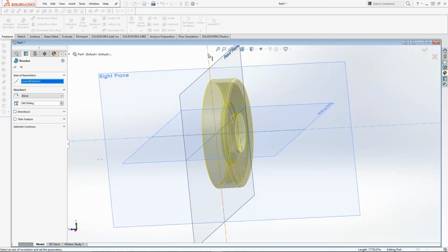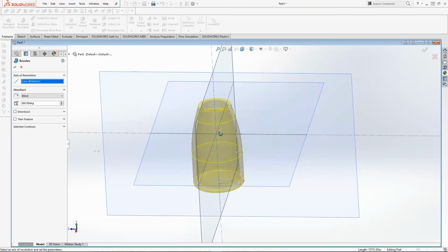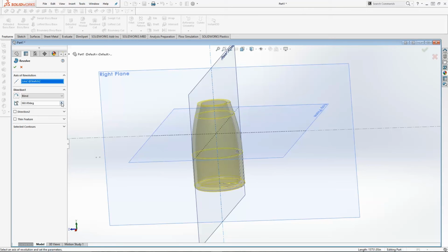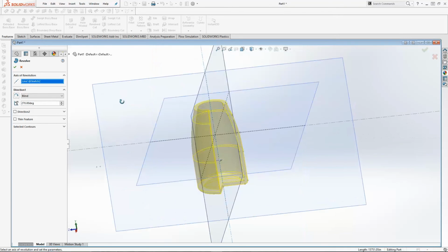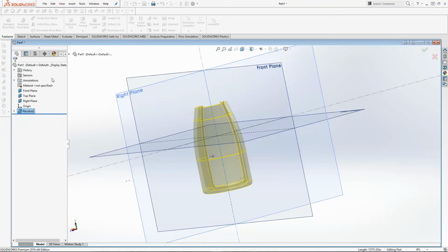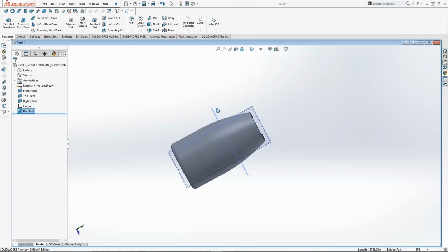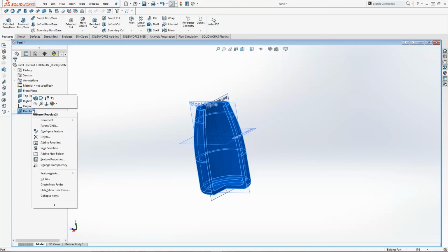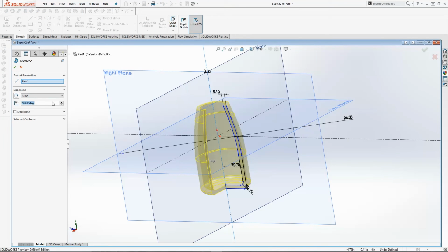But for right now, we're going to do it around this one because that's the shape we want. If you only wanted like a quarter, then we could do 270, and get that 3/4 shape. So you get that different perspective on it. You can go in here and finish it just by editing it and putting that 360 back in.